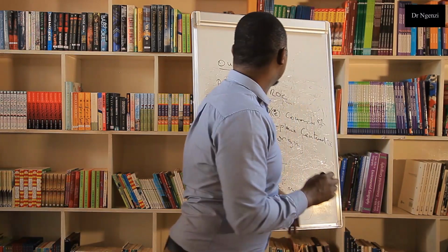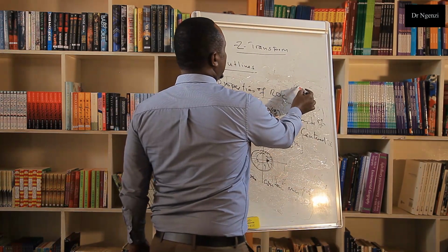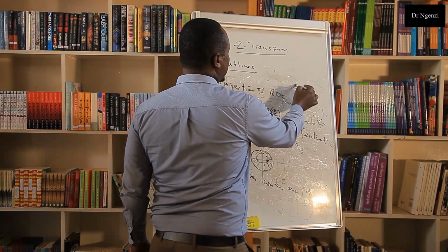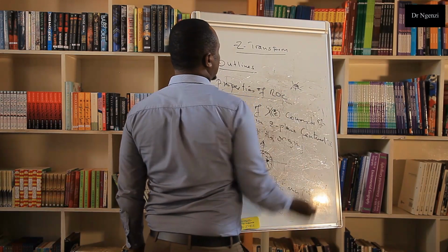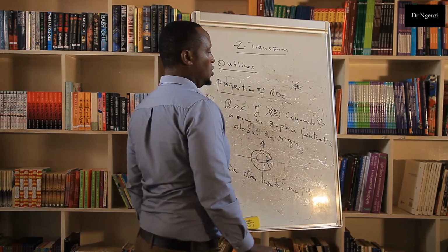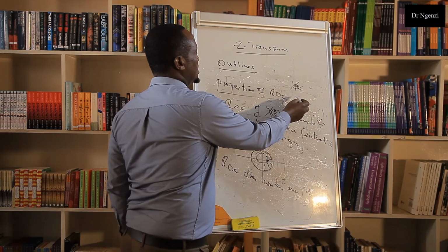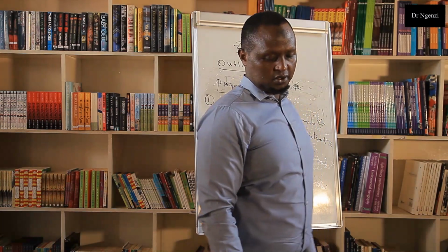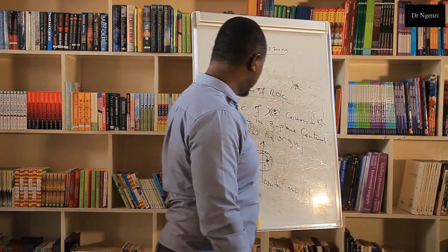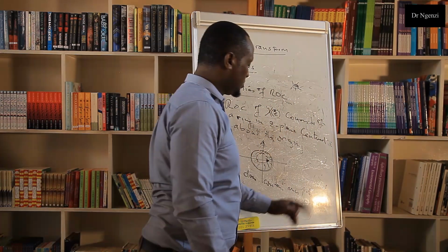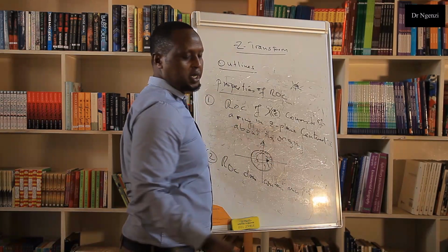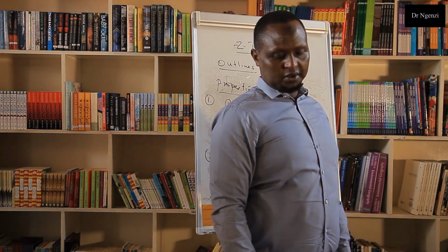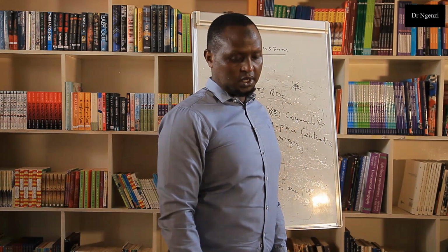Whenever you see the pole sign, you cannot begin from there. Instead, the region of convergence is going to be external to these poles, or just before it reaches these poles. That is property number two: it doesn't contain any poles. Remember how we get the poles? They are the denominators of the fractional expressions of the Z transform.